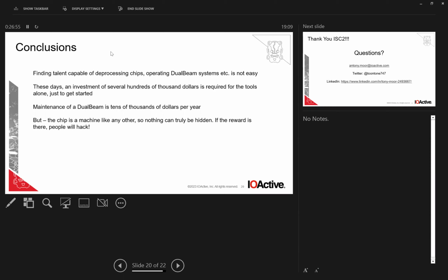If it was something enormous, there are techniques that you can use to localize the part that you're interested in. You can use techniques which will, transistors emit photons and heat. So you can look at them or look through the back of the device while it's running, and you can get signatures that will build up over time. And it tells you that when you're talking to it and asking it to do things, the activity is taking place geographically in a specific point. So maybe you only have to reverse a smaller part of it.